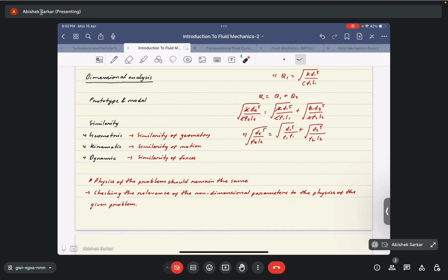This is basically the local Reynolds number of the flow. It is u infinity x over nu. This is a non-dimensional number that could define all the physics of the problem, obtained by clubbing these parameters together into a single non-dimensional number. That is the local Reynolds number in the case of flow over a flat plate.